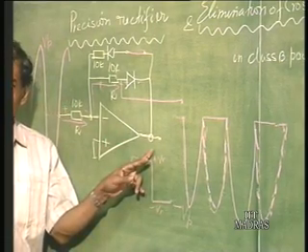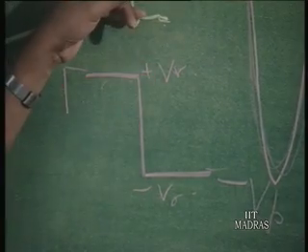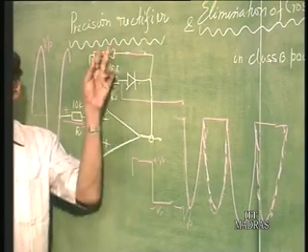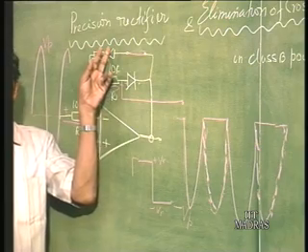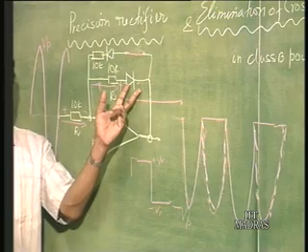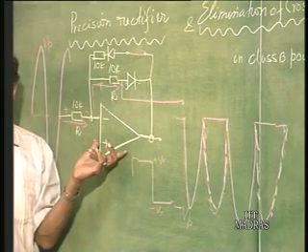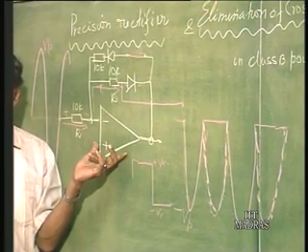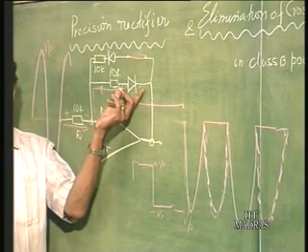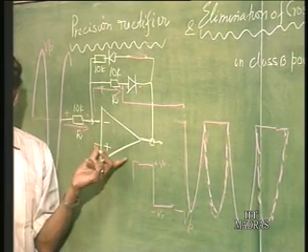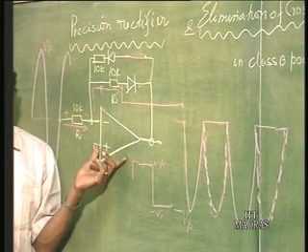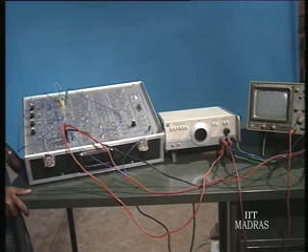So, the op amp comes into picture, jumps to plus V gamma and minus V gamma respectively, so as to make these diodes conduct. That is why the conduction of the diode is independent of its cut-in voltage as long as the gain of the amplifier is very high, and therefore, we are able to use a practical diode in the negative feedback path and get a rectifier which can rectify even millivolts of peak input voltage. So, this demonstration is going to be done there.